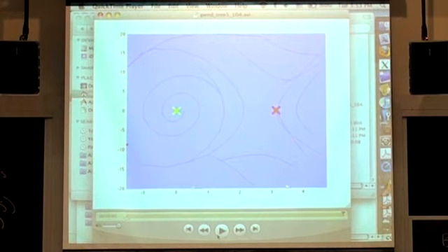There's a couple things you could try, and actually I recommended to Mike earlier today that he should do this for his final project, to do the case with the actuator limits. You can imagine making a soft limit, some sigmoidal limit, and having the gradients of that visible from your linearization point. Or you could imagine the LQR design that actually does both the quadratic cost and the bang-bang simultaneously. Haven't done it yet, but I think that's consistent.